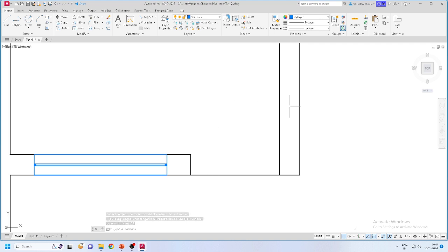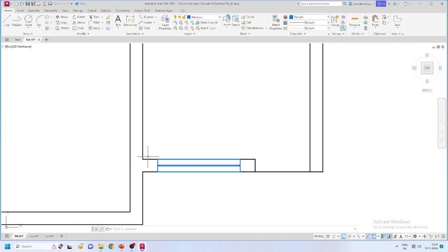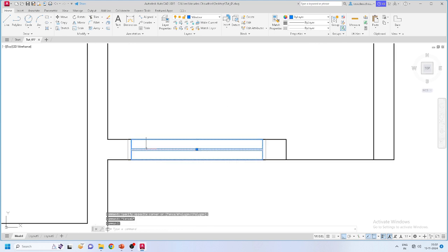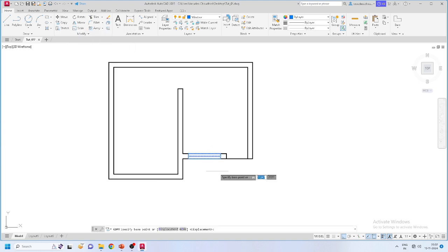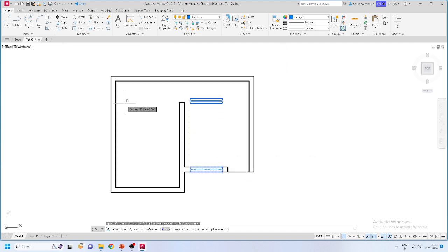Further, you can even provide the door as well. So now what I can do is select this window and group it, right? So all objects will be grouped now. Even if I select one part, all the relevant parts of that window will be selected, and then I can use copy. I can put this window at some other location also. Let me keep this off.